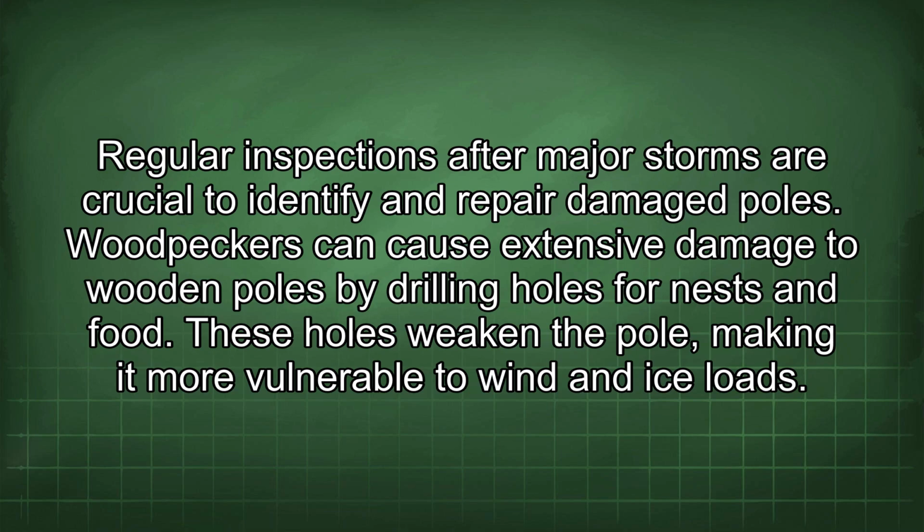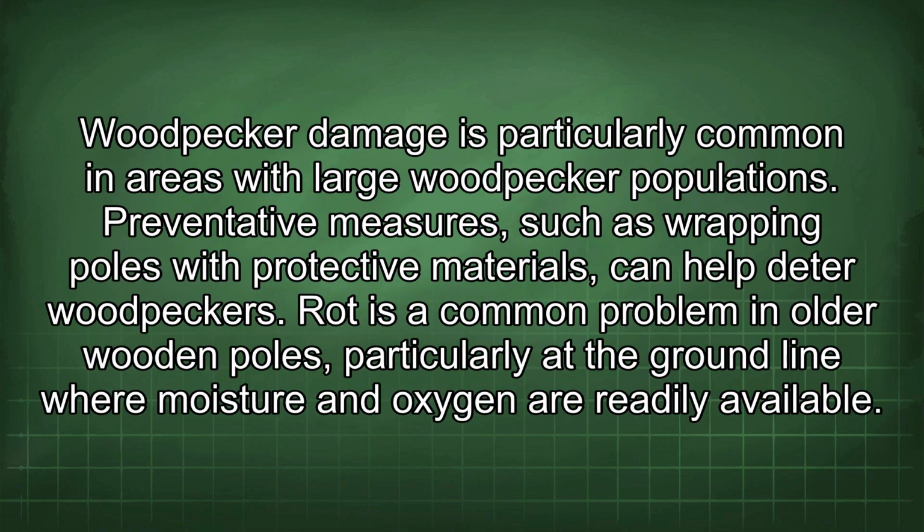Woodpeckers can cause extensive damage to wooden poles by drilling holes for nests and food. These holes weaken the pole, making it more vulnerable to wind and ice loads. Woodpecker damage is particularly common in areas with large woodpecker populations. Preventative measures such as wrapping poles with protective materials can help deter woodpeckers.